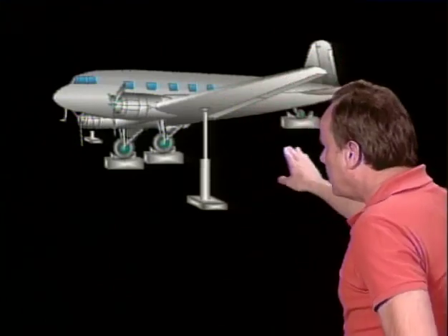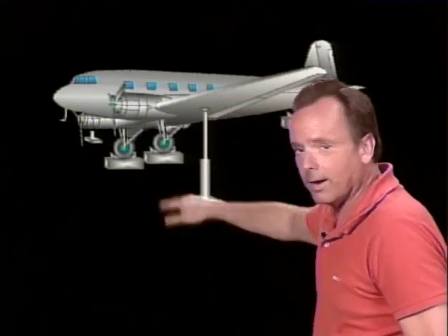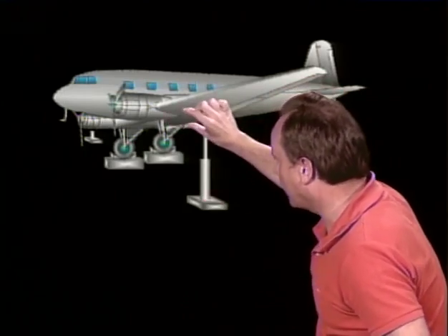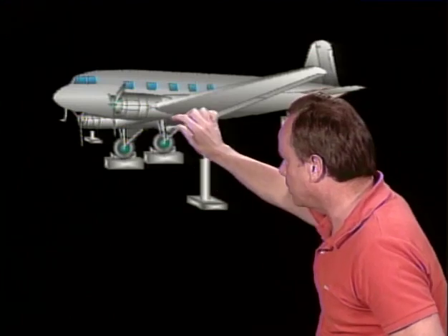Now let's assume you want to jack up an airplane to weigh the aircraft for weight and balance purposes, and you're going to do it with a magnificent DC-3. The question is, should you do it indoors or outdoors? And they want you to generally jack up aircraft for weighing indoors. They don't want the wind to affect the weighing of the aircraft. And also they want you to know, before you jack an aircraft, you need to reinstall any critical stress panels or plates, because if you have load-bearing stress panels off the aircraft and you jack up the aircraft, you could put a stress on other parts of the aircraft that it's not designed for.